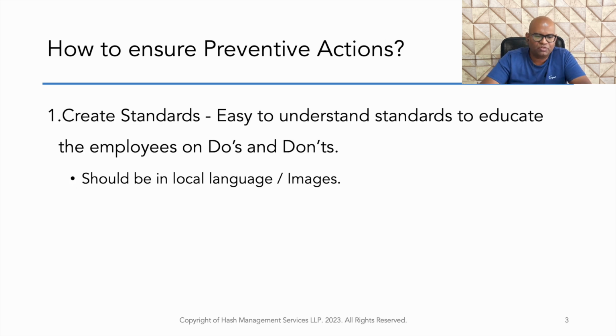preventive actions. So the first one is creating standards. What are standards? Standards are a step-by-step method which somebody can follow to ensure that that particular operation is done in a proper manner. When I follow a standard, the product quality will be better. And that's what everybody is supposed to follow. That is called a standard. Standard in Tamil we call it Seimure Vilakam, a step-by-step method to do that particular activity. If you write down step-by-step, for example, take this particular piece, load it here, and ensure that the temperature is this much. Like this, if you can give it point by point, that itself is a standard.